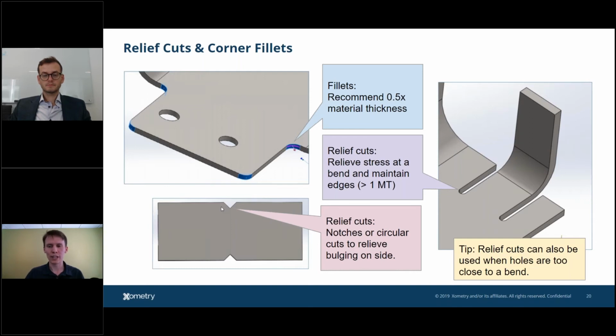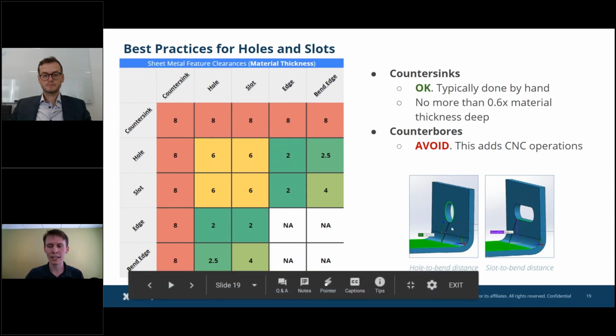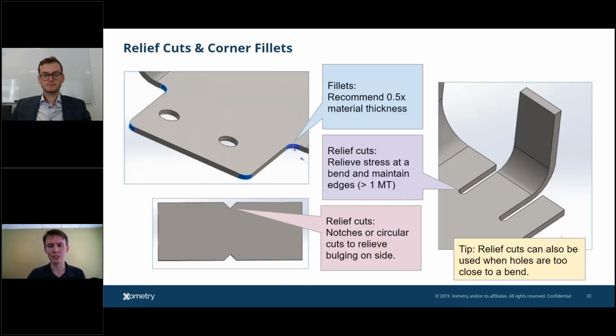I'm also going to note, running back to my best practices for holes slide, sometimes if your hole is a little closer to the edge, I could do a 0.5 millimeter laser cut, basically a little relief cut right below it, almost like an underscore, parallel to the edge there. What it does is that little underscore is going to flare out, but your hole won't. So sometimes you can do that to mitigate for holes that are not right near the edge.